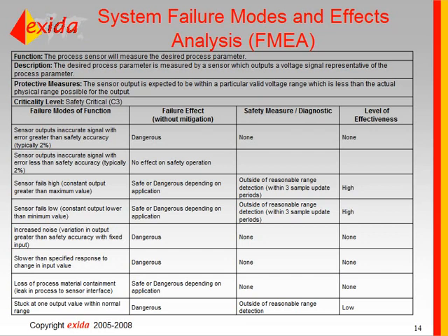we're going to calculate some actual numbers to determine whether the product meets the requirements for the safe failure fraction and for the probability of failure on demand. So during this phase, it's just a guideline that if you can have medium effective diagnostics on all major faults or all significant faults, then you're really likely to be able to meet the requirements or be close to meeting them at the end. But if you're not exactly there, if you're not sure at this point, you'll find out later on in the process. So it's not a hard requirement at this point.